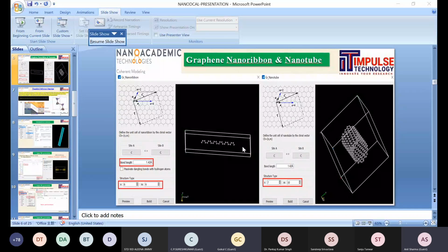Now, if you want to perform some doping in a particular number of atoms, either N-type or P-type doping, or you want to define some mole fractions and concentrations to create some alloys, it is a very simple procedure, and based on that you can find different behavior of chemical structures. You can dope a particular structure or create an alloy, like with the indium arsenide material. If you want to substitute gallium in the indium arsenide, it is very easy to substitute the new materials to create the defect.